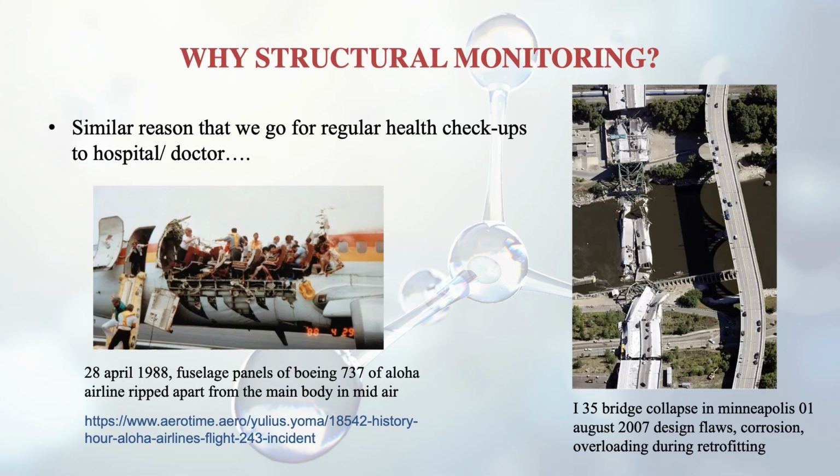The underlying cause of this accident was later found to be the appearance of multi-site cracks in the skin joints. These led to the unzipping of large portions of the fuselage. They were undetected during the routine pre-flight inspections. So these two accidents lay emphasis on structural health monitoring of civil engineering infrastructures, mechanical systems, and aircraft.